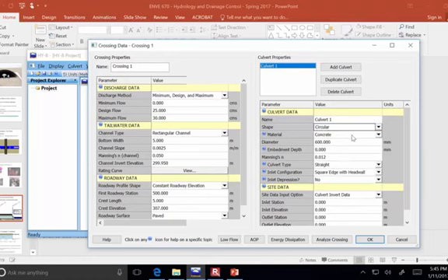But ours is circular concrete. Embedment depth is talking about how deep into the base the culvert may be put. I'll just leave it at the default value of 0. This Manning's N value is determined by the material, so 0.012 is a typical roughness for concrete.